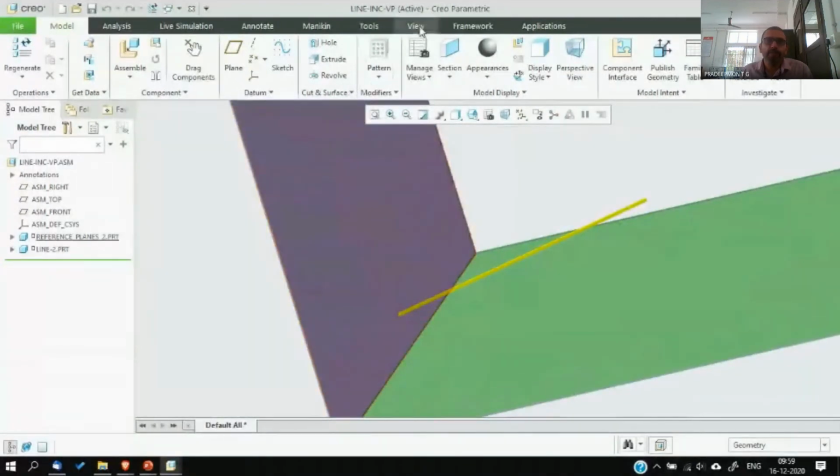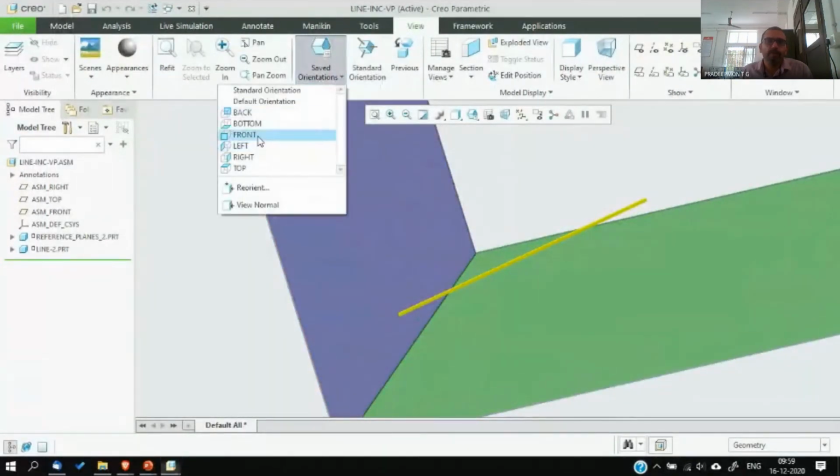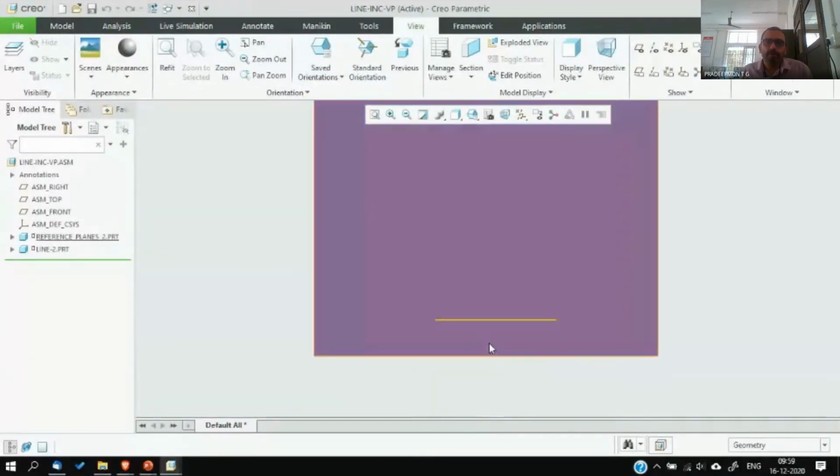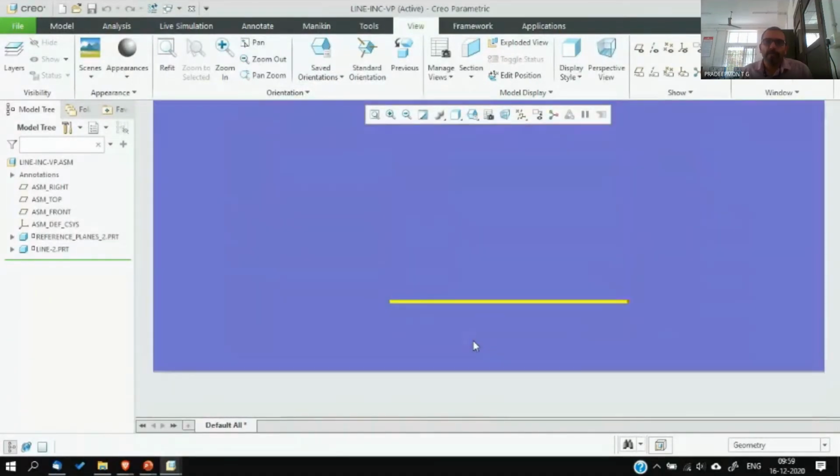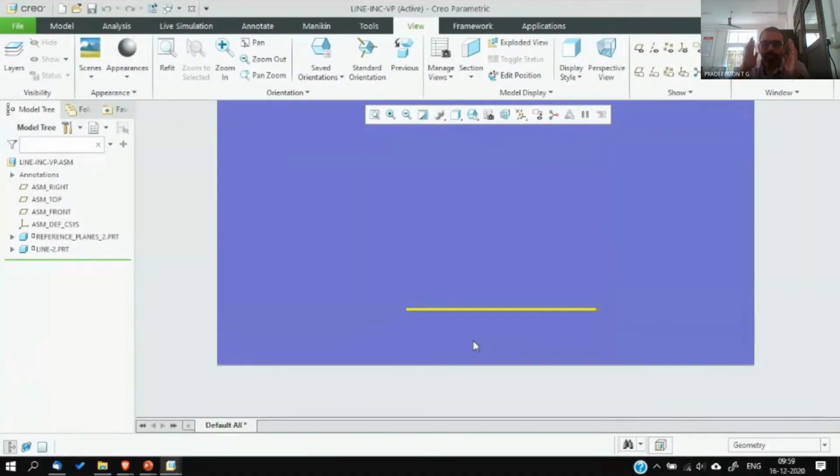If we go to the front view, see, the front view is parallel to the XY line. The length of this front view will be a reduced length with a factor of cos phi. So this length can be found out by the true length multiplied by cos phi, where phi is the inclination of the line with respect to the VP. Pictorially, if you want to find it, you have to draw the front view. So in this front view, you get the reduced length.